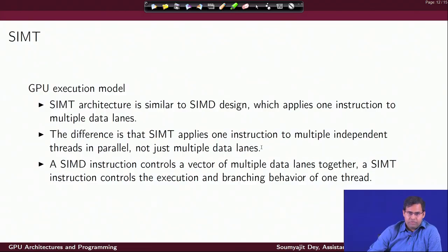For the time being, just remember those two pictures that we are discussing, that overall the idea is very simple. When I talk about SIMT, it is just like saying, let us generalize this concept of single instruction multiple data and start thinking that you have instructions operating across multiple programs, or their lightweight versions, that is threads, and all the threads are making progress in lockstep.